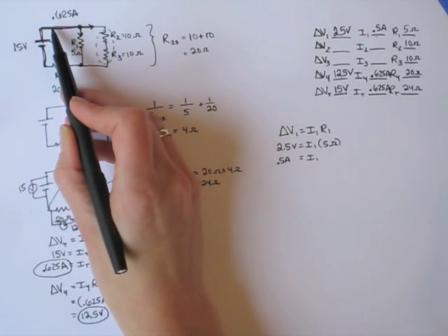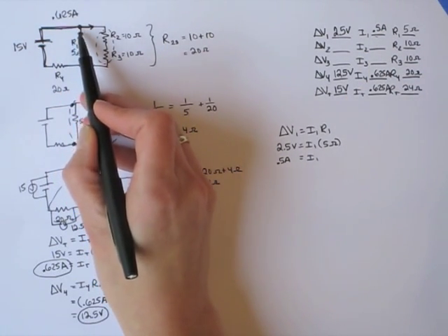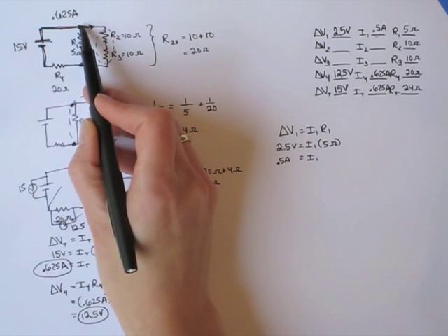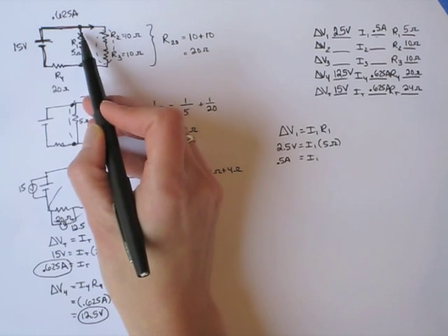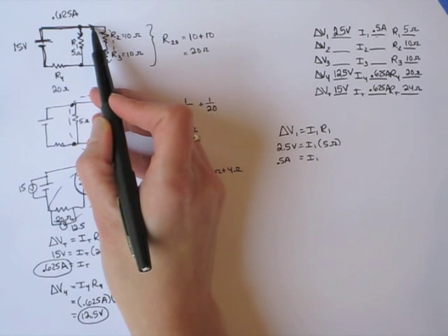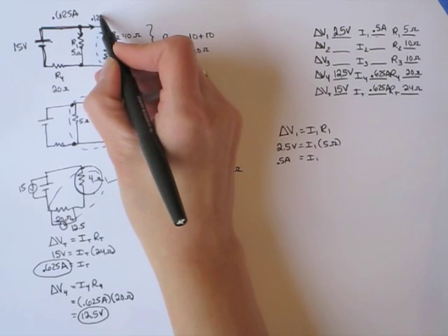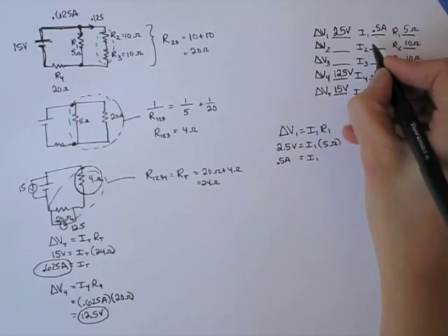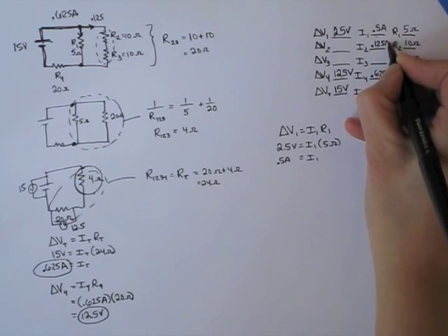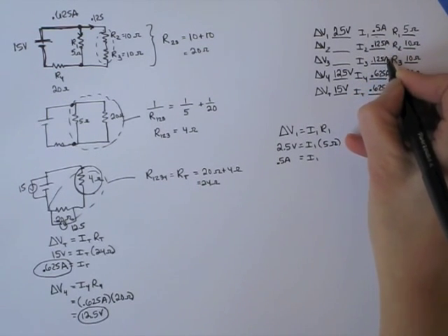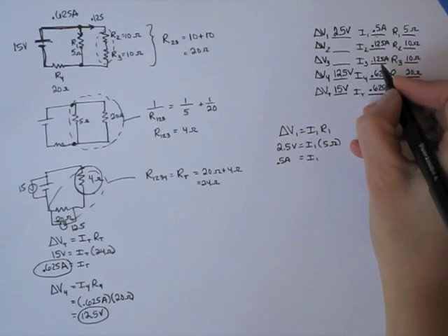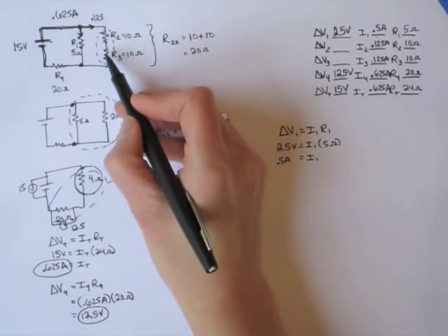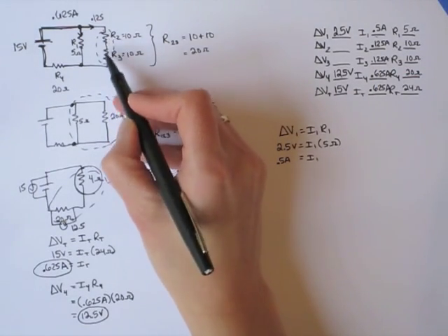And we can see that the flow in 0.625, it's going to divide. So if part of it goes here, the rest of it must be here. So if this much was 0.5, this over here must be 0.125, because together they have to add up to the 0.625. So this must be 0.125 amps. Now that we know the flow, oh, and the flow is the same in both of these because they're in series with each other.